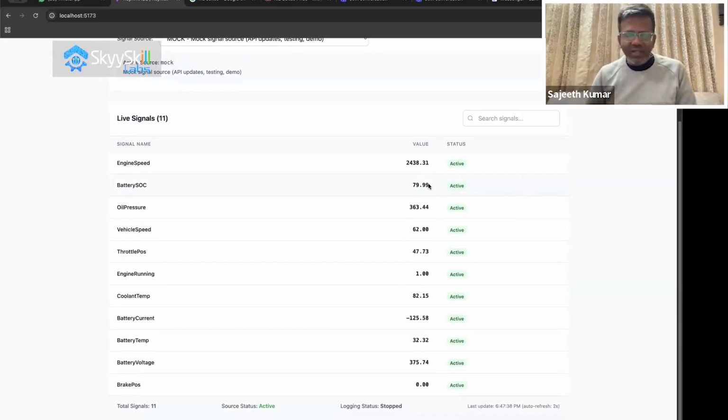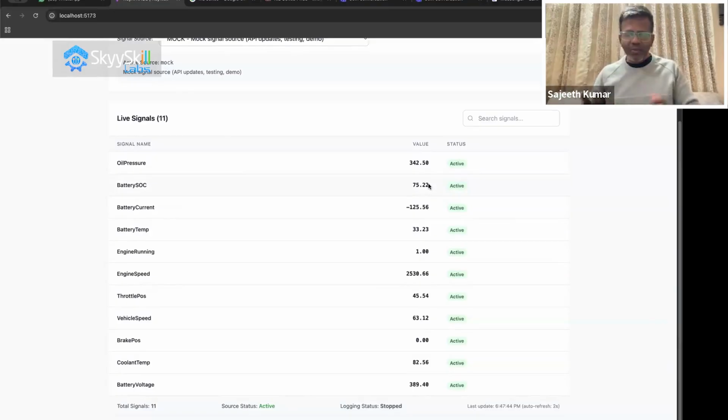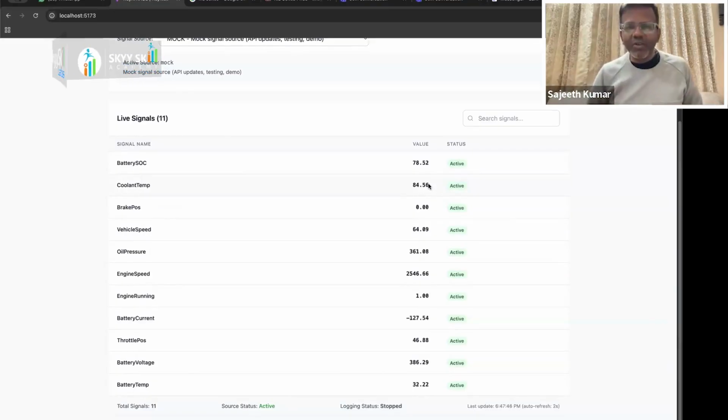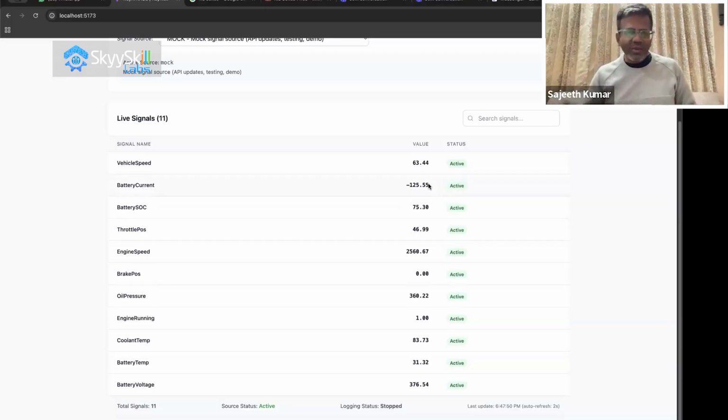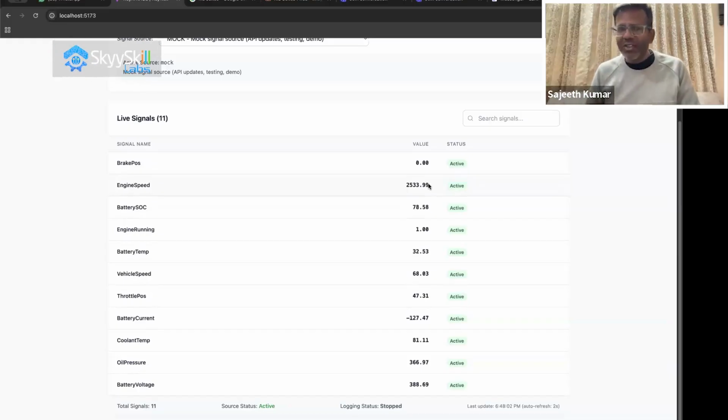Now, how do you understand this? Right? So what you can think is you build a diagnostic software, you build a MATLAB Simulink model. You're going to learn about MATLAB Simulink and modeling tomorrow, I guess. Siddhant, my colleague, would probably be talking about it. So you can build a model in MATLAB Simulink. You can convert all of those signals virtually into a CAN signal. You can feed it to a diagnostic stack and you can build your diagnostics algorithm. Right? So how cool is that?